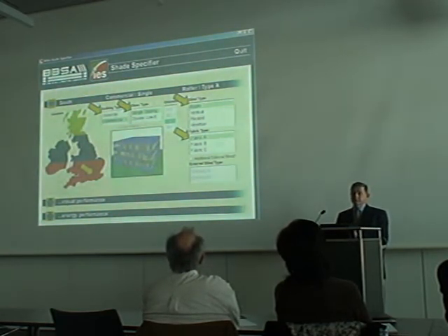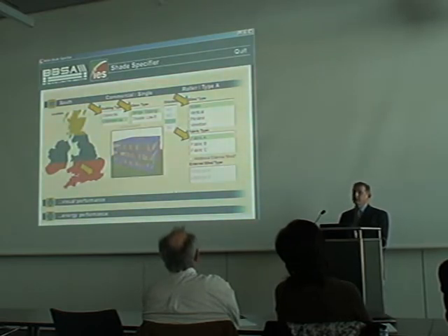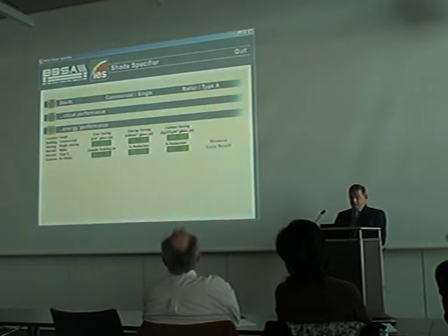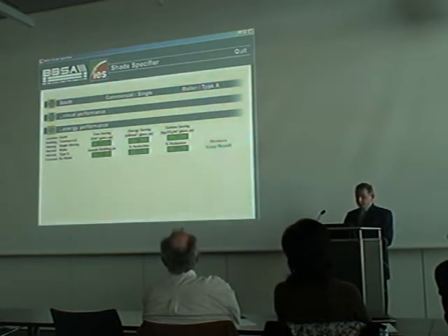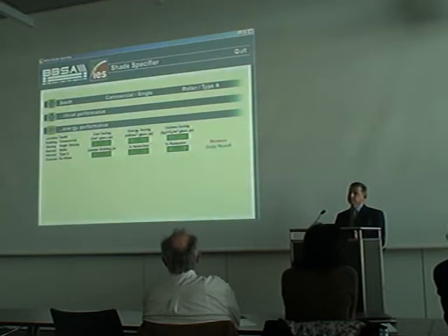The weather data happens to be London. It's a commercial building with single glazing, and we're putting a roller blind in those windows with a fabric type A. And if you hovered your mouse over this fabric type A, it would tell you that it's a highly reflective fabric. And that gives me an energy performance here, where you can see that potentially on that model building we have saved 9.4% of energy, and we've saved 15% of CO2.